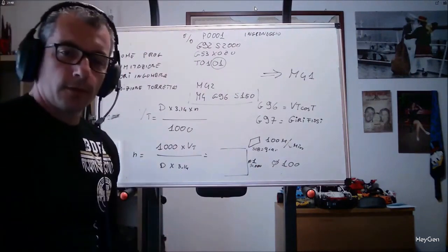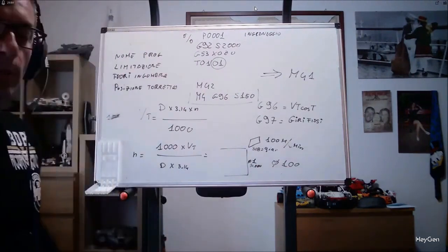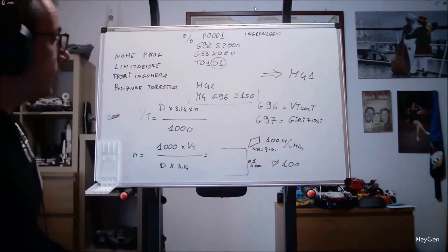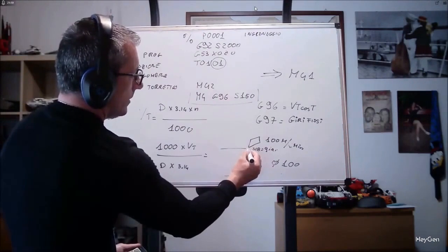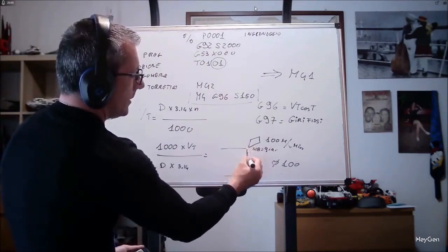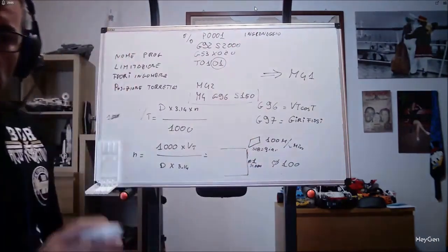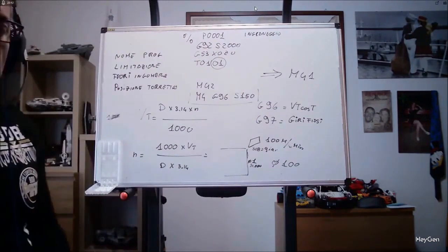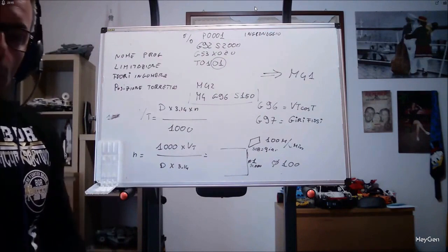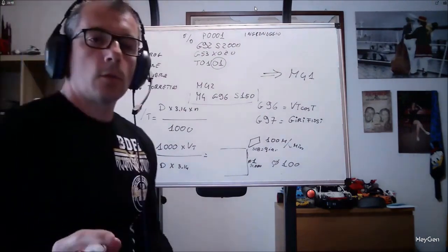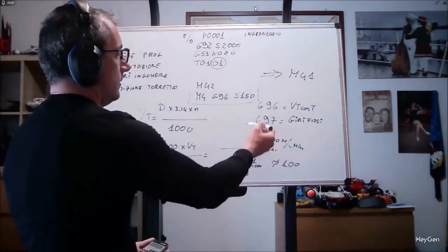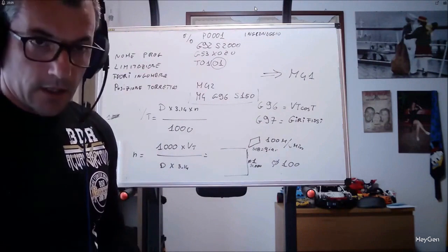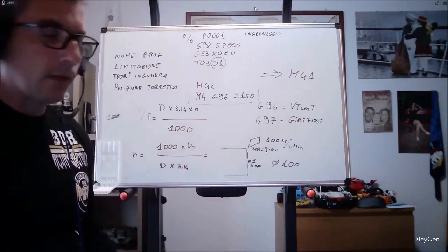It is quite obvious that a lathe, perhaps of large size, at 31,000 revolutions will break apart. You will find screws on the ground. That's why the machine will slow down and increase its revolutions as it approaches the center until it stops. Here is the difference between constant cutting speed and fixed revolutions. If you are already working in the workshop, just perform a facing operation to physically feel the machine accelerating as it works towards the center.